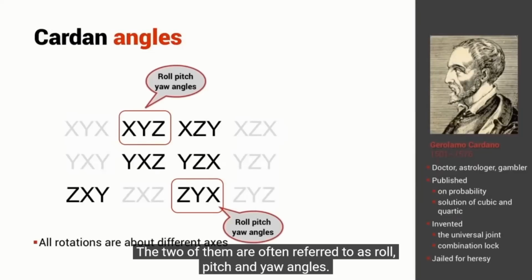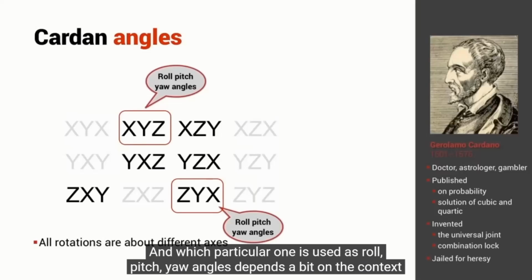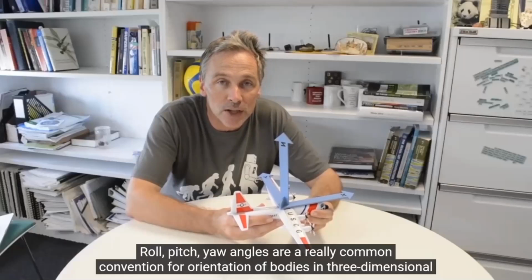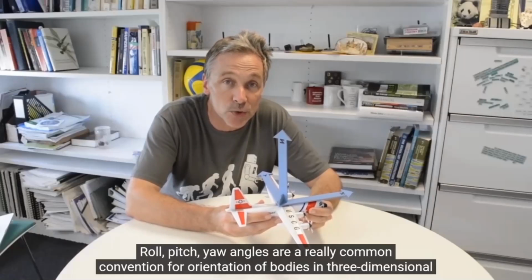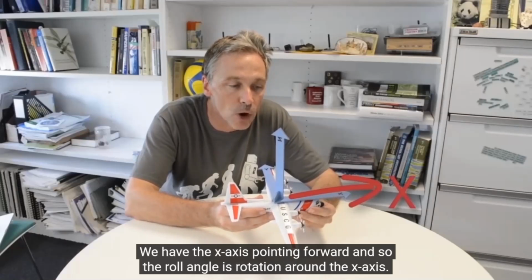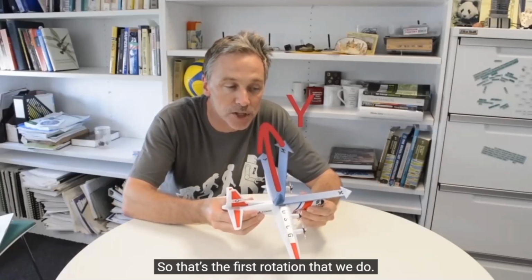Two of them are often referred to as roll, pitch, and yaw angles. That's the sequence XYZ or the sequence ZYX. Which particular one is used as roll, pitch, yaw angles depends a bit on the context of the problem. Roll, pitch, yaw angles are a really common convention for orientation of bodies in three-dimensional space. We have the x-axis pointing forward, and so the roll angle is rotation around the x-axis. So that's the first rotation that we do.